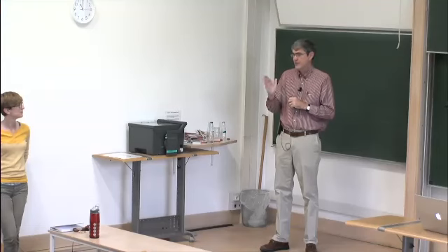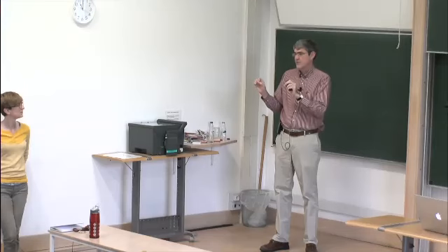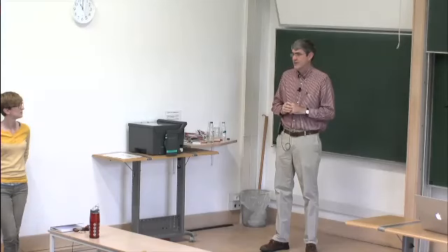So the Riemann solver at a particular cell edge would depend on the state variables on the two sides, but the velocity at the edge would define the velocity at which that propagates into one cell or the other.